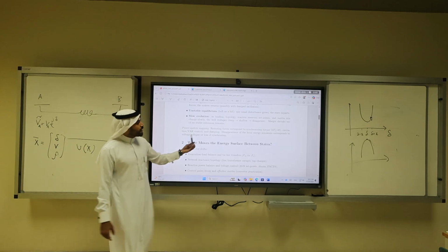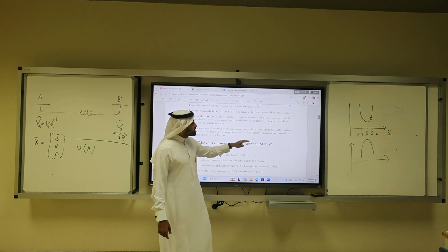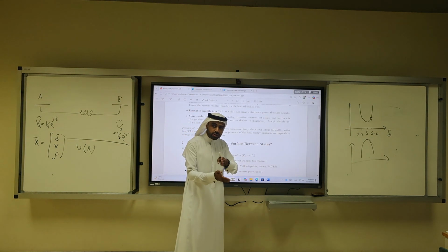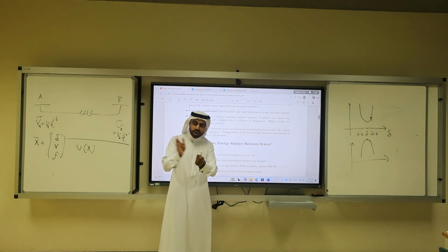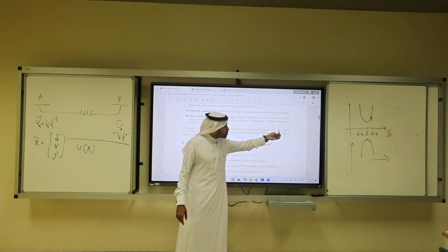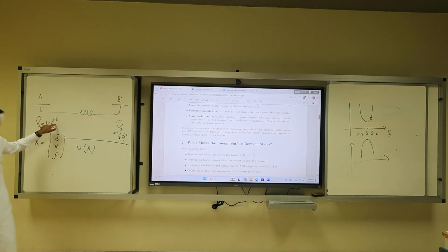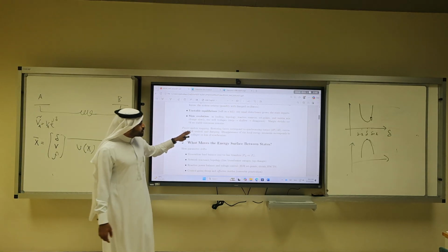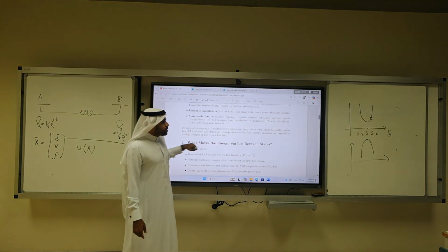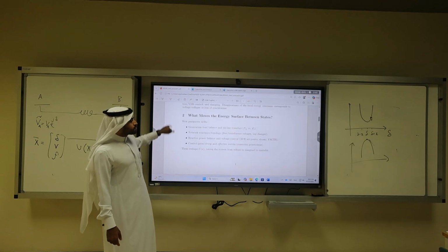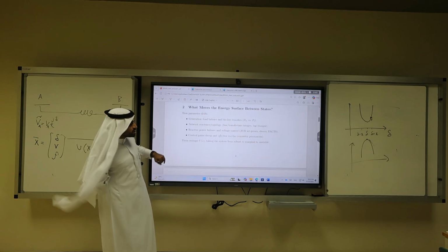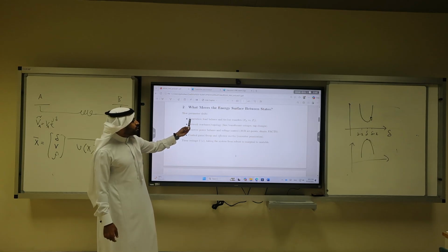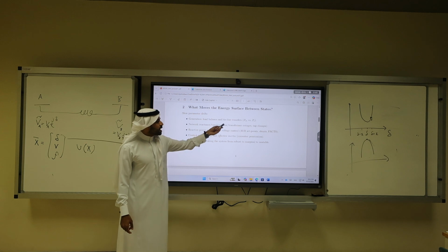So based on that, you can restore forces, for example, you change the torque. If the electrical power changes, if a generator power changes, how much of that impact would change the delta angle of this voltage? The other thing is the excitation control and damping. That's very important to study. Now, what moves the energy surface between states? Sometimes we have generation, load balance, and tie-line transfer.